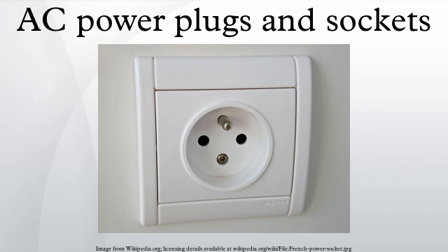US perpendicular socket. Another obsolete socket, made by Bryant, 125V 15A and 250V 10A rating. A NEMA 5-20 125V 20A or 6-15 250V 15A plug with a missing earth pin would fit this socket, but a NEMA 2-20 plug is slightly too big to fit.